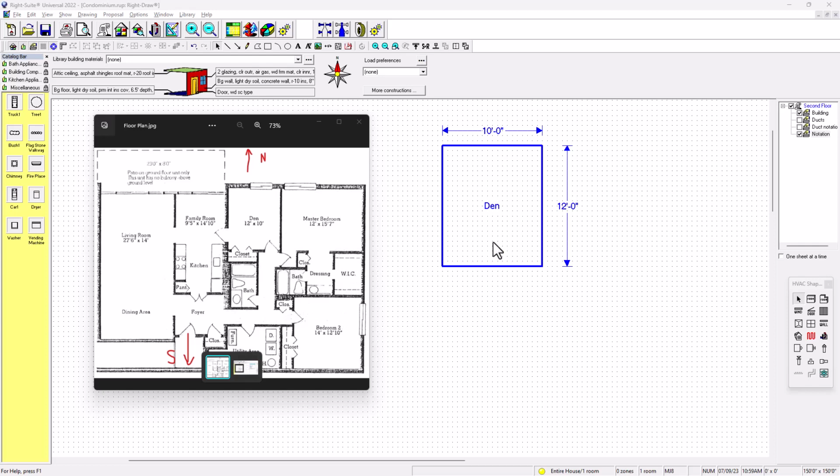This might be a bit of a long process because we need to put a lot of detail on the dimensions. These lines don't have thickness. However, the exterior walls actually have thickness, sometimes 8 inches, 1 foot, depends. So if you rely on your interior dimensions, for example, this master bedroom is 12 feet by 15 feet 7 inches, then you are not accounting for the exterior wall.